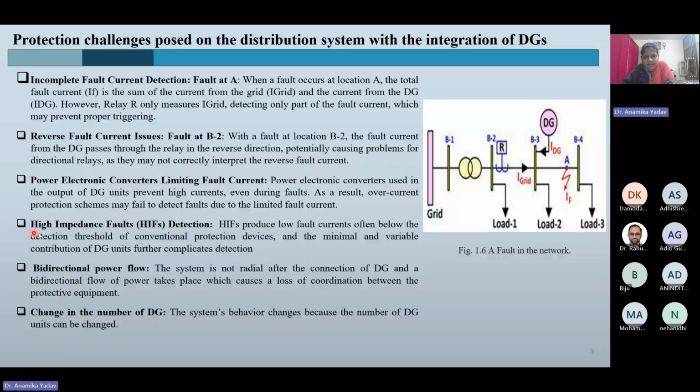And if the system is subjected to high impedance fault conditions, this is a very crucial type of fault, wherein, due to the high impedance nature of the particularly ground types of fault, the faulty current amount is not considerably high. So that may come in the range of the normal overloading that may happen, till 10 to 20%. So it may remain undetected if a high impedance fault occurs, with the conventional scheme.